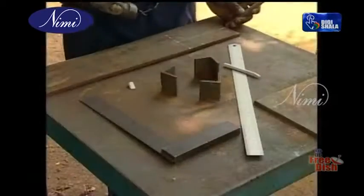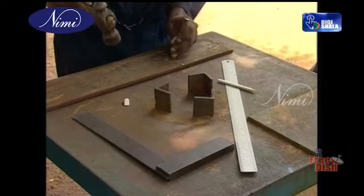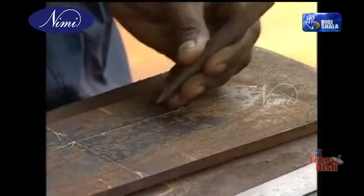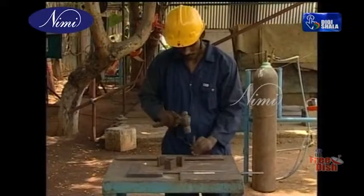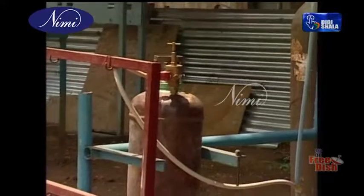Once the marking is completed, the welder uses the center punch and indents the dimension points. Now the specimen is ready for oxygen acetylene gas cutting.